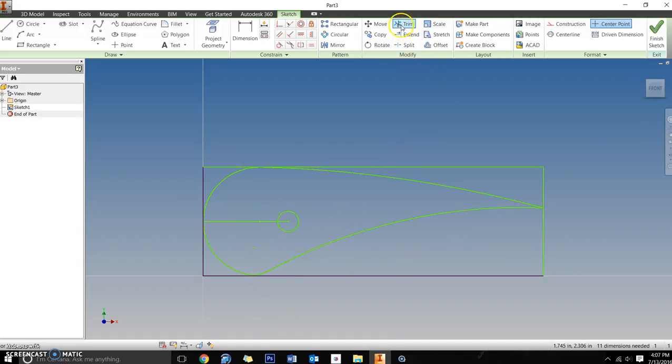And then when I delete some of these line segments out of here, I'm going to my trim tool, which is in the modify panel, and I'm just going to trim those out of there. I'm just clicking with my left mouse button, deleting those all out. So I'm basically left with my overall design here.